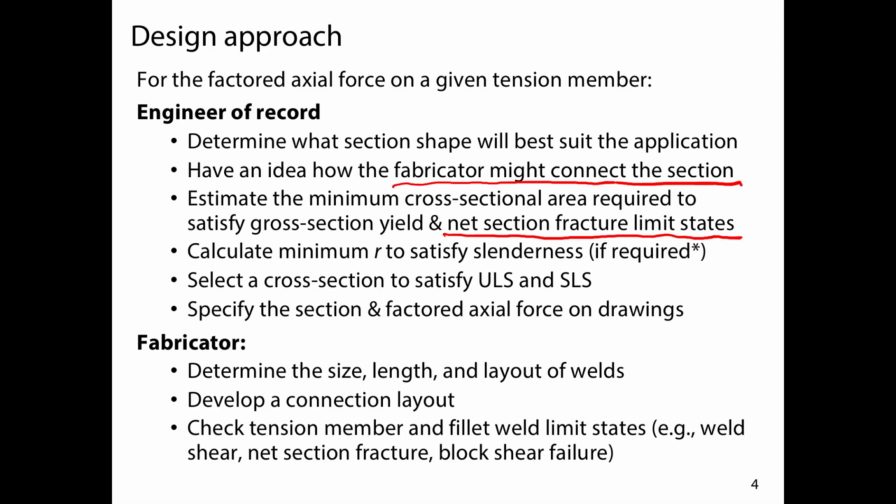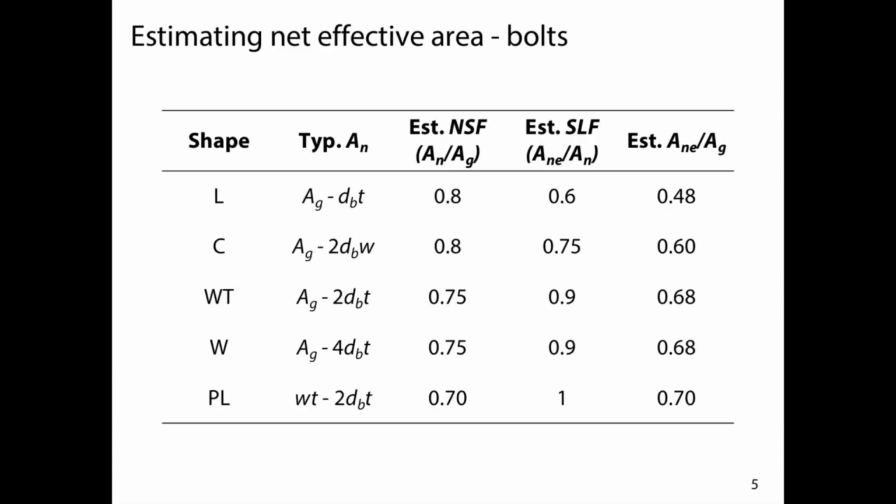I don't know why necessarily. I think everyone just bolts them. And S16 doesn't provide explicit guidance in determining the shear lag factor for welded WT sections. So you should know some of these things.